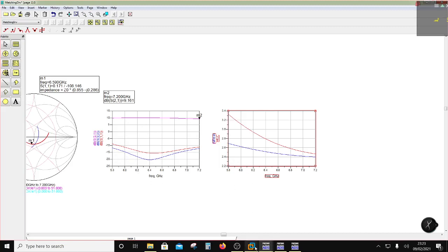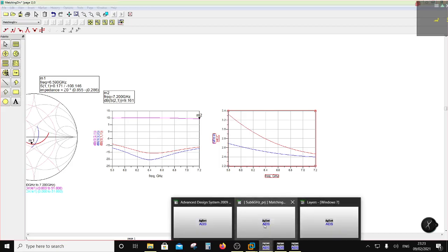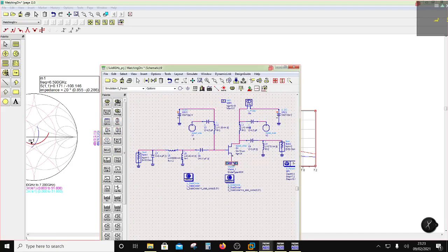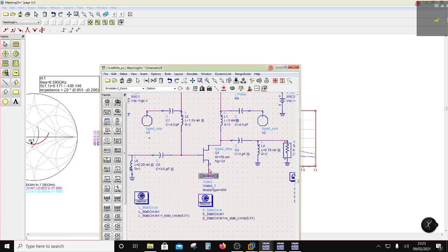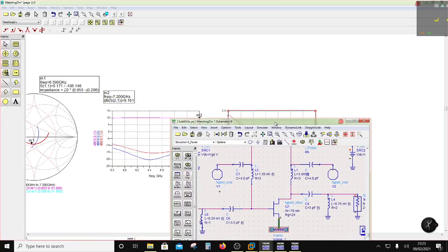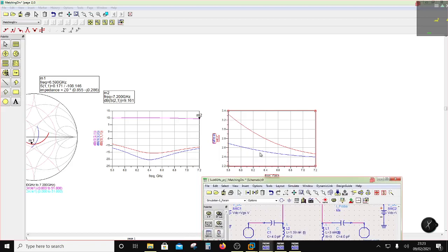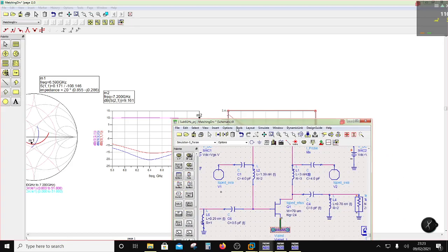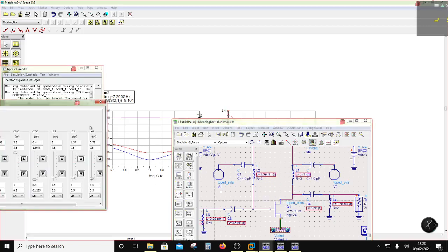Okay, so you can tune for the noise figure, but what is going to happen is if you change the source inductance, you improve the source degeneration, then the noise figure is going to improve, right? So for example, and the stability will also improve, but the gain will go down, right? So let me just, if my target is 1 point something, right, then these numbers are really bad. So let me just put a tune on this one.